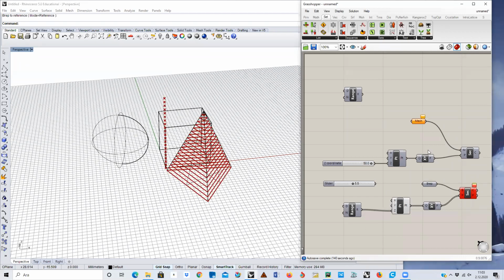And on the other hand, you can also use meshes. And for mesh, once you use meshes like STL files, the thing is that you need to have a different intersection, let's say, component. Here we are using BREP and plane intersection, but for the meshes, obviously, we need to use mesh and plane intersection component.